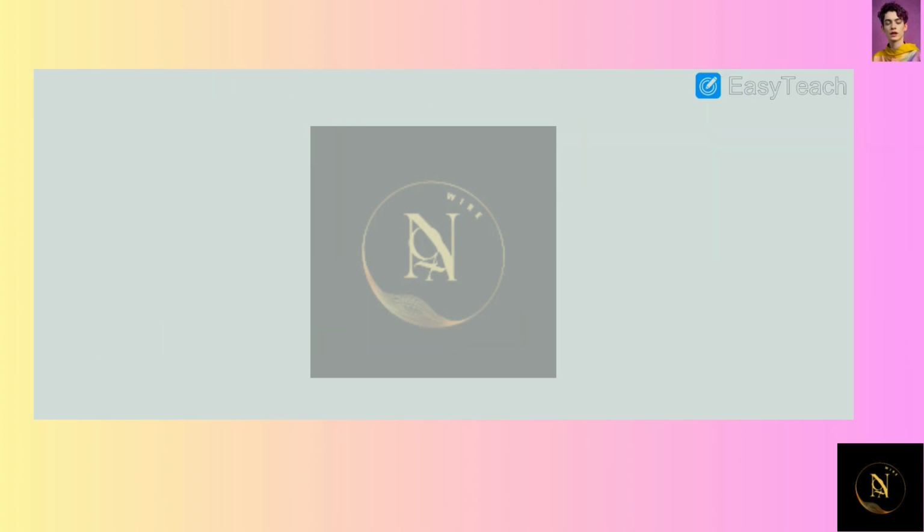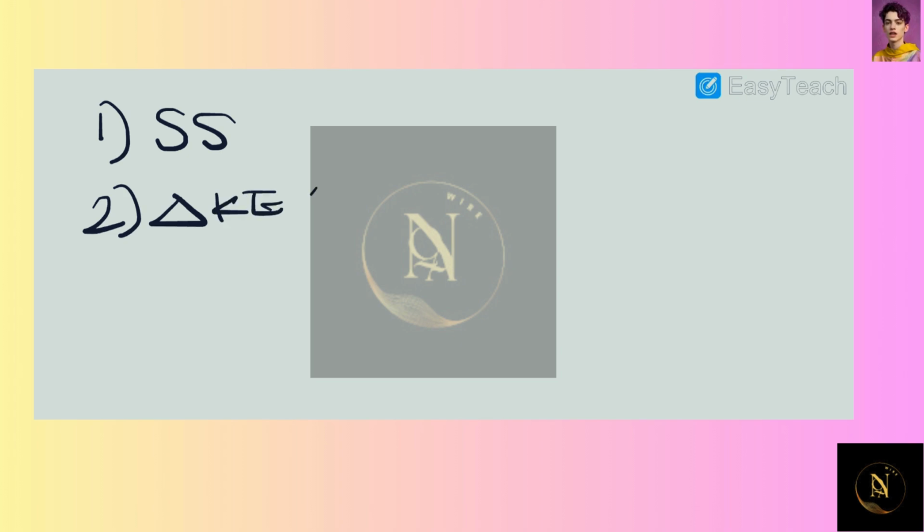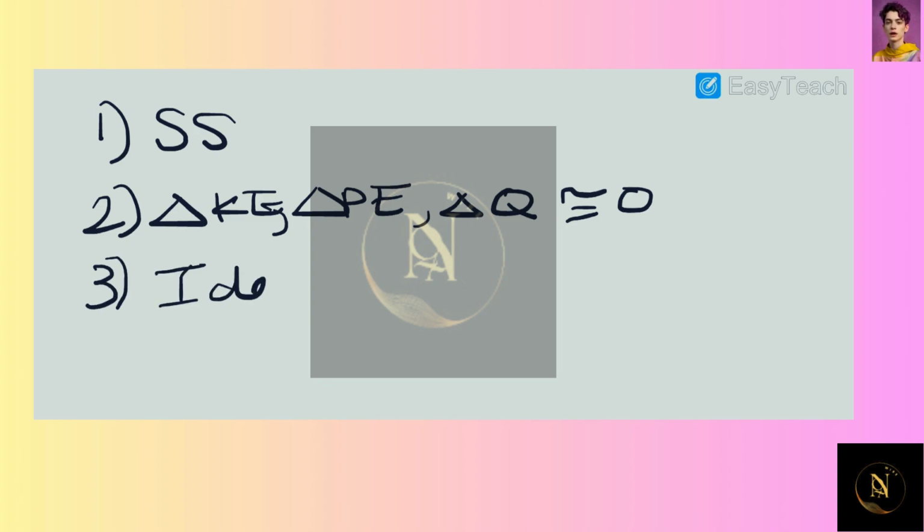The first thing we're going to do is go ahead and write down our assumptions. We are going to assume this is a steady state process, so properties will not be changing with time. We're also going to assume that any changes in kinetic energy, potential energy, and heat transfer are going to be equal to 0, because we do know that everything is adiabatic. And we're also going to assume that air is an ideal gas with variable specific heats.